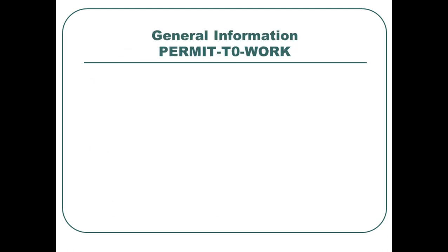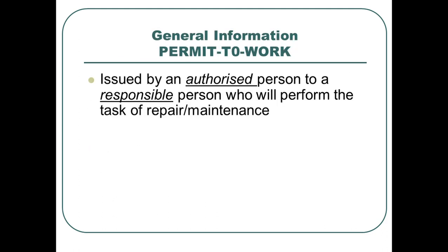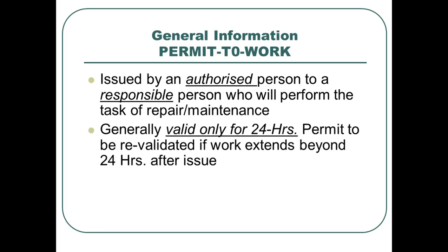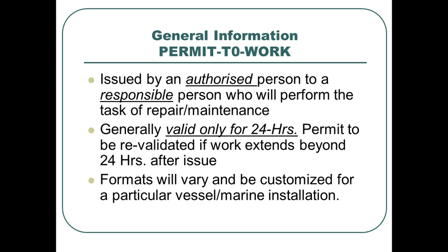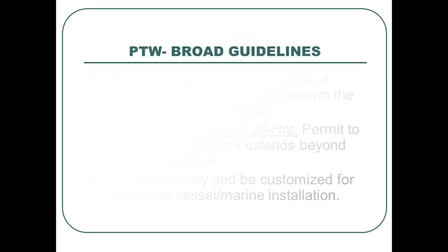We will see what is polarization index separately. A permit to work is issued by an authorized person to the responsible person who performs the task for repair or maintenance. It is generally valid only 24 hours, and the permit is to be revalidated if work extends beyond 24 hours after use. Formats will vary and be customized for a particular vessel or marine installation.